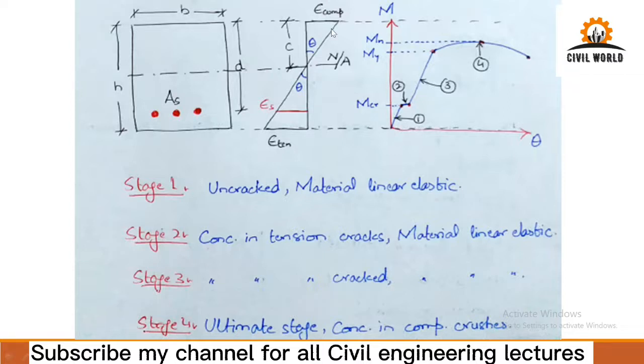Here your strain profile goes from compression to tension. And the distance from the top fiber to the neutral axis is C. You have this theta, which is actually the curvature of this beam. As the load increases, curvature increases. So compression strain increases, and this theta increases.